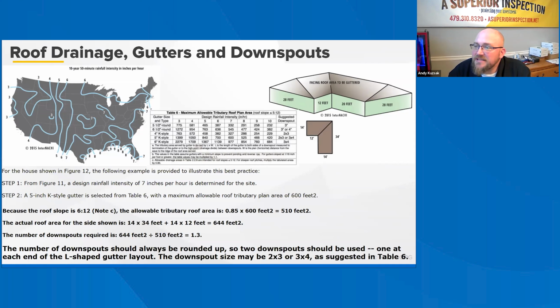If using suggested sizes for downspouts, the gutter size will generally control the spacing of the downspouts. Downspouts with a dimension of less than 2 inches should be avoided. It is also generally recommended that downspouts should serve no more than 50 feet of gutter length. A commonly used gutter is the 5-inch K-style gutter with a 2 by 3-inch rectangular downspout.